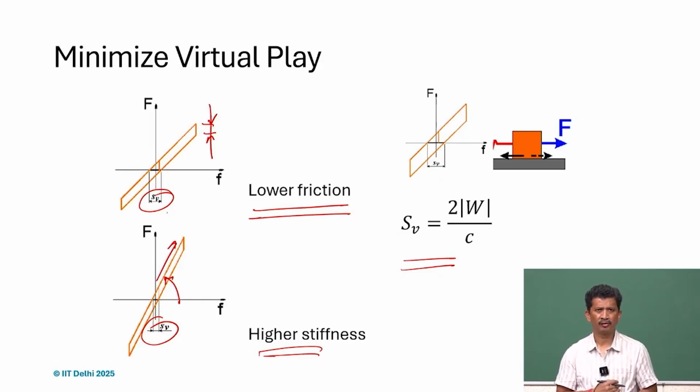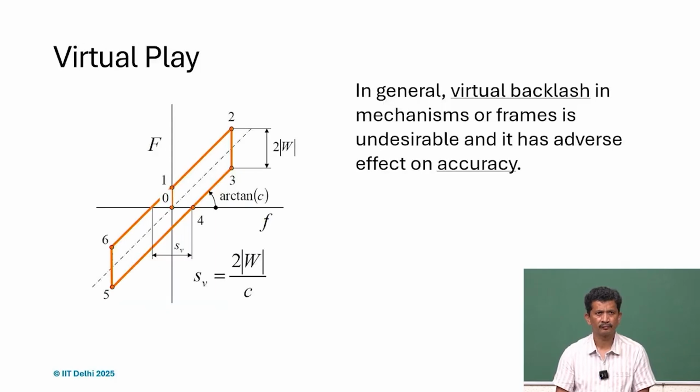And what we also realize, this is the reason we are talking about compliant mechanisms or flexure bearings or other kinds of bearing, so that we can avoid any kind of friction force. So a very simple example: one body connected with the elastic member, with the elastic structure, and this is the kind of play we will get even though there is no physical clearance or gap between the components.